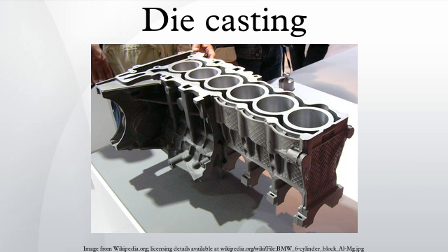The advantages of this system include fast cycle times and the convenience of melting the metal in the casting machine. The disadvantages of this system are that it is limited to use with low melting point metals and that aluminium cannot be used because it picks up some of the iron while in the molten pool.